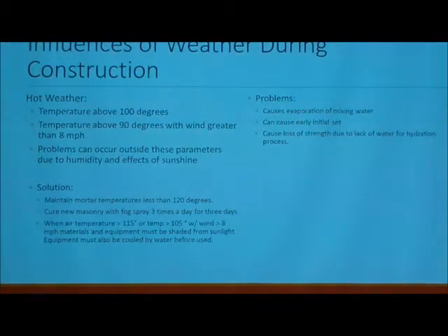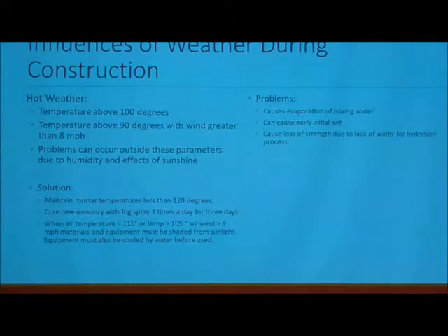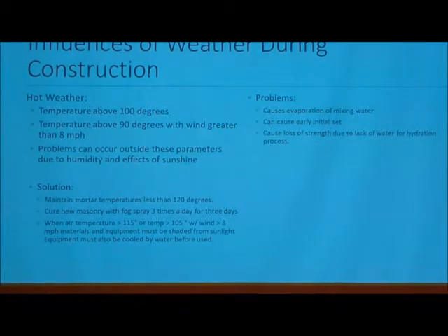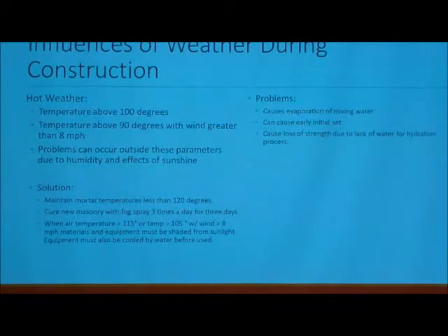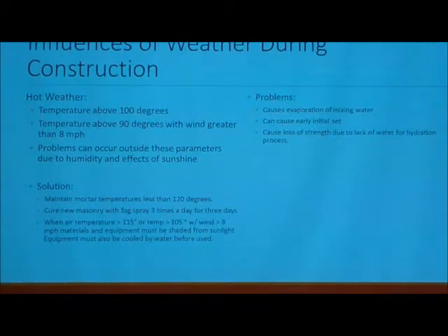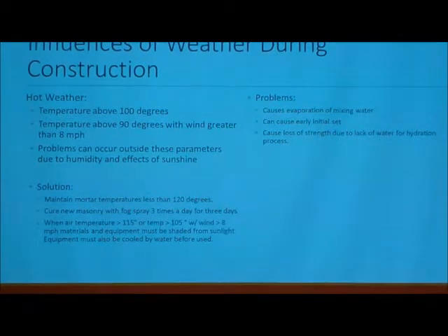Okay. For hot weather, which is temperatures above 100 degrees or temperatures above 90 degrees with a wind greater than 8 miles per hour, you have certain parameters that you have to watch out for too. Some of the problems with that is it causes evaporation if you're mixing water inside the grout, and that will lead to early initial set or loss of strength due to not being enough water for hydration.